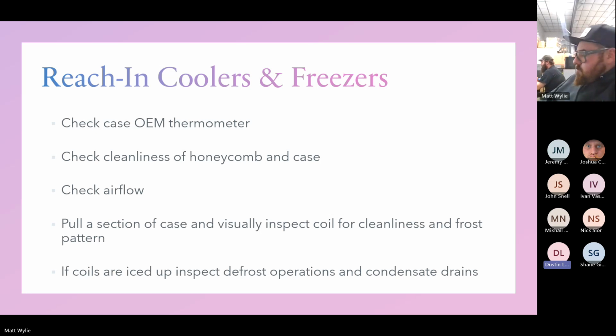And like we were saying, there are lots of scenarios. John mentioned drip time, but another thing is defrost termination. How many of us have de-iced a freezer, thrown it into defrost, took a quick amp reading and was like, oh, my heaters are working, must be good. It's probably a clogged drain.